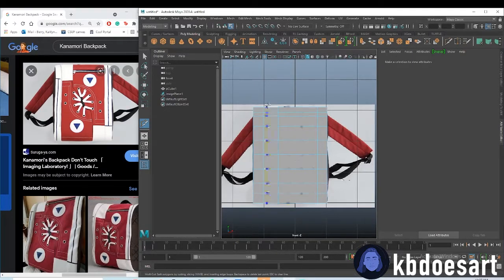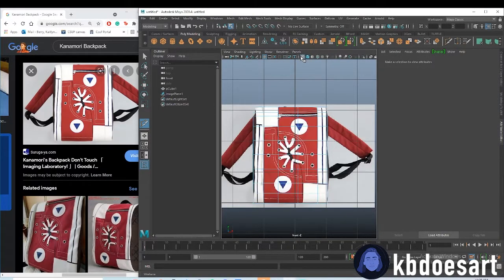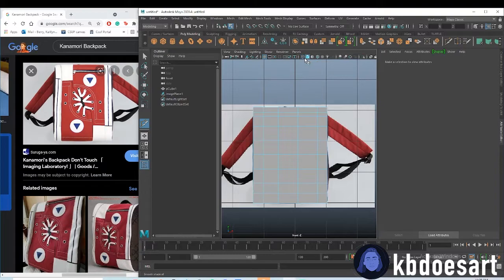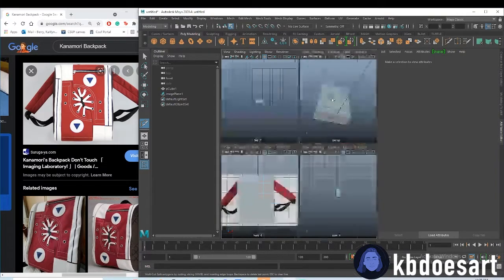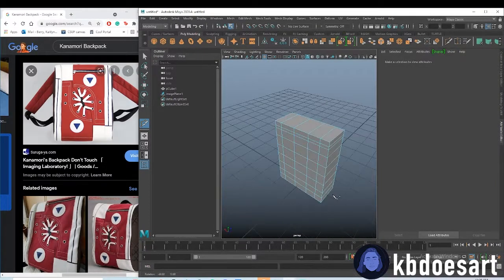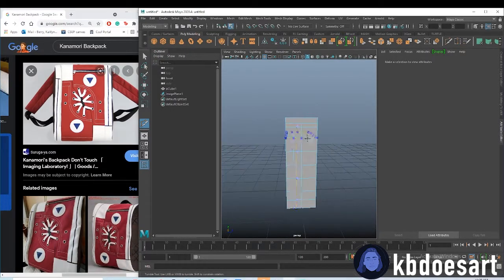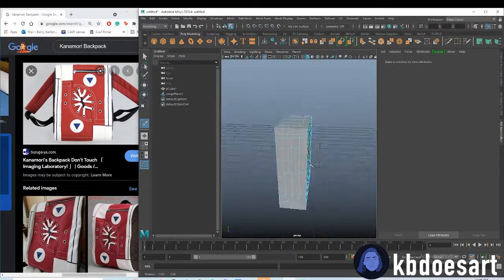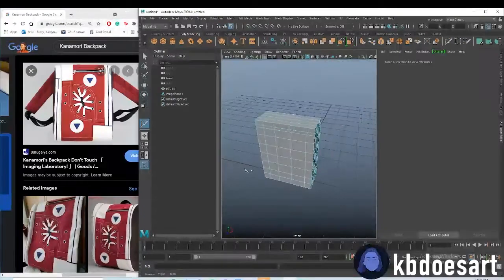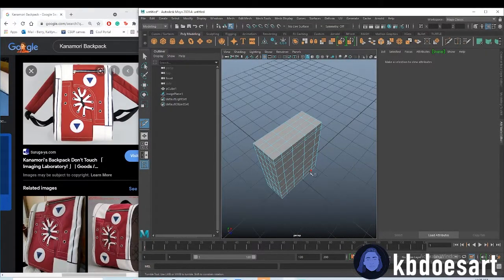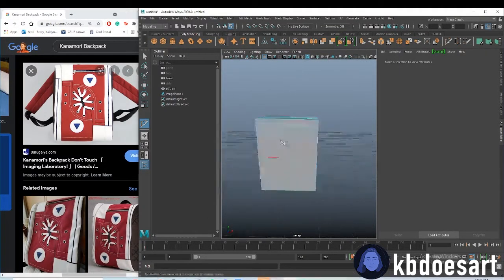So that's how many cuts I just threw in real quick. And then I'm going to middle click again right here to split that as well, just to get a quick base of multi-cuts for us. And then if you click space and go in here, we'll add 4 like that, which is just me literally holding control and clicking the middle mouse button.